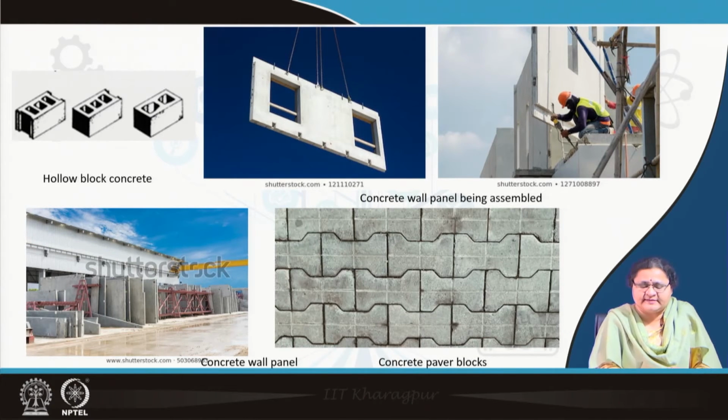What more you notice is the opening that may receive a window, but that cannot be done by way of assembling bricks and creating an opening. It has to be done before. So, the design of the entire thing has to be done prior. Your door location, window location, opening location, every detail should be given to the factory, and there should be enough of such orders to satisfy the economics of the entire thing.